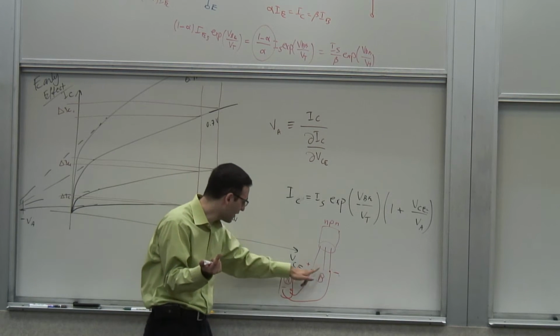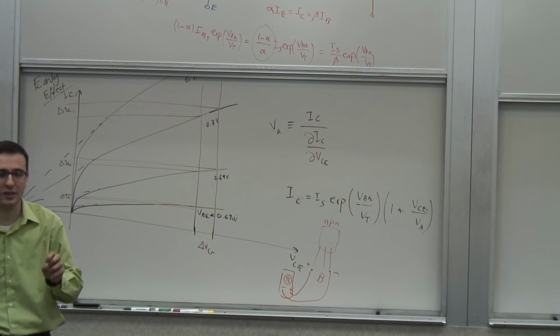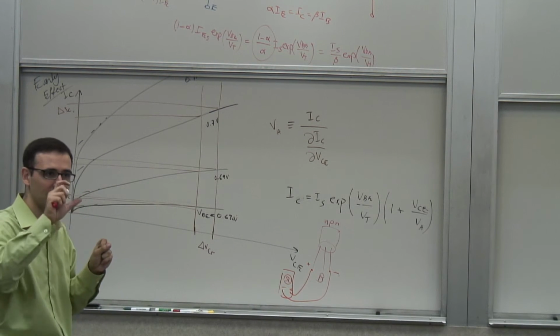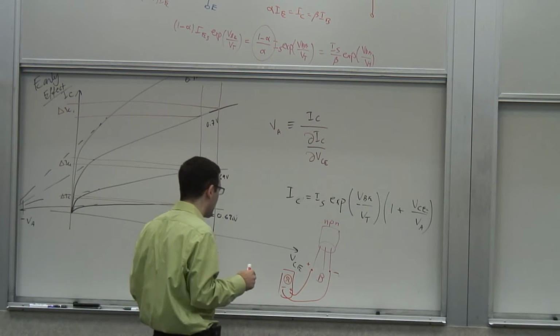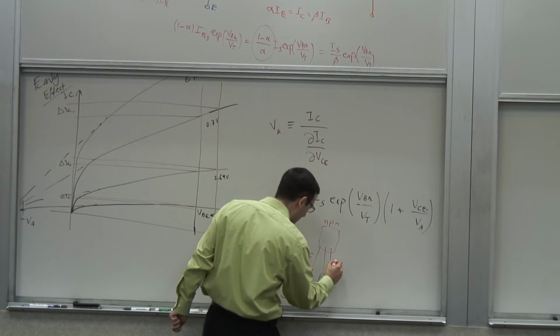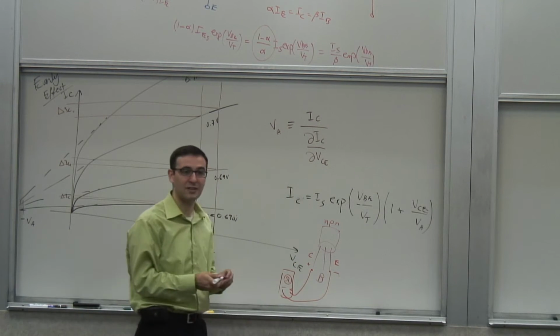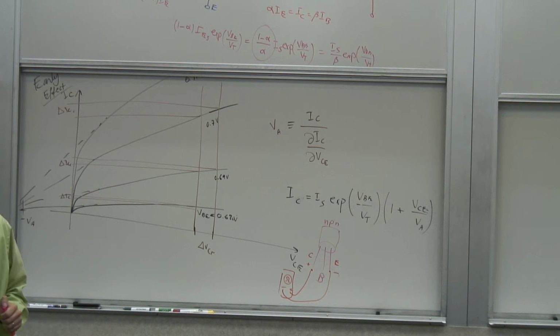But now I touch the base. And if I see a change, if I see some current flowing, if I see the resistance is non-infinity and drops to some finite value, I claim that if it's an NPN, then this is the collector, this is the emitter. If it doesn't, I reverse the polarity, and in that case it should. Tell me why that's the case.